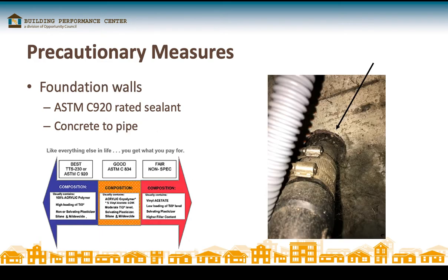All right. Here's a picture of a drain that goes through the foundation wall below, and there's a gap around it. That's below grade, so soil gas can come out of that hole there. And we are going to use some of that rated sealant to caulk that gap and stop any airflow that might be able to come through there.